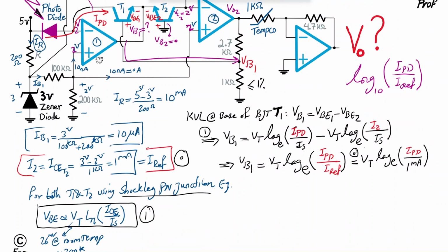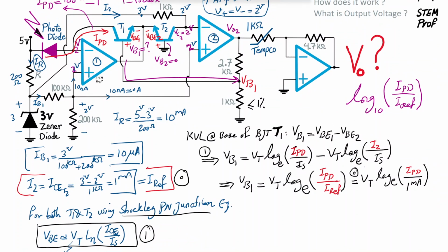Okay, with that, now let's see. Given the current that the base of the transistor is taking, I base 1, the current that goes through the base is very small. These transistors have beta or HFE, the current gain, collector current divided by base current, on the order of greater than or equal to 200. These are small current transistors.